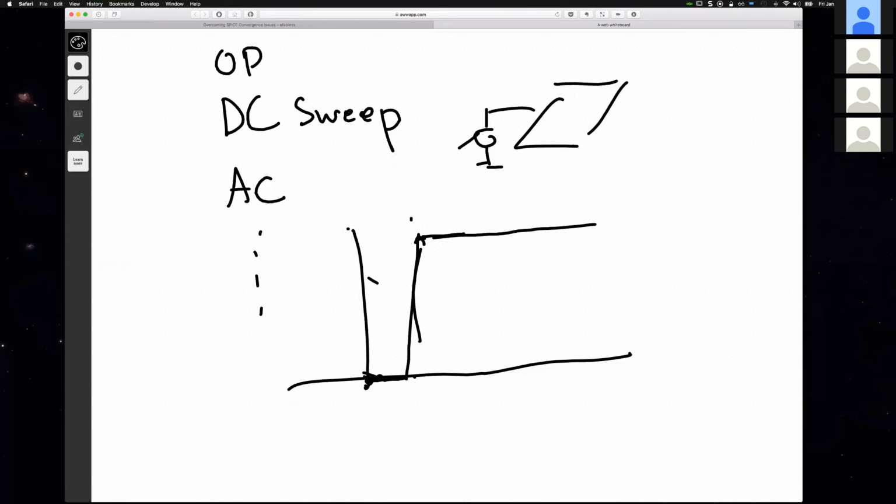Now, some circuits intentionally choose, and one of these cases would be here, that enabling the circuit would wait until the supply and the system have risen to a certain state. They intentionally want to make it a power down state, a standby state, where some of the nodes are forced to 0, so you can have a completely controlled scenario rather than letting it be alive with the supply. And then you enable it, maybe, and then you have a signal that would trigger other activities in the circuit. So that's the real world, and it happens this way.